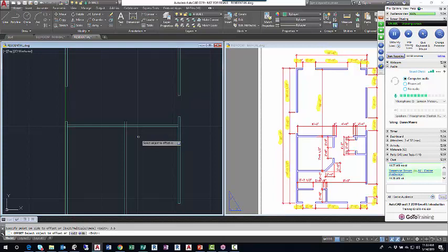So there's my 3.5 inch line. Then I'll left click that new line, move right, type 6, enter. So there's that line. Left click that new line, move right 4 feet, enter. Left click that new line, move right 6, enter. Left click that new line, move right 3.5, enter. And as I said, I shouldn't need to do the 2 foot one, but I'll try to measure it.